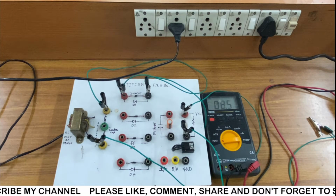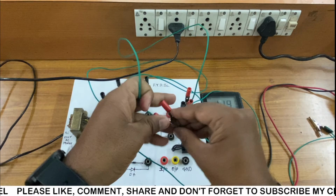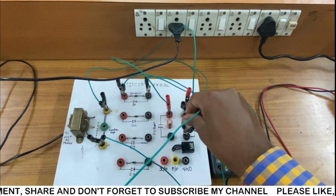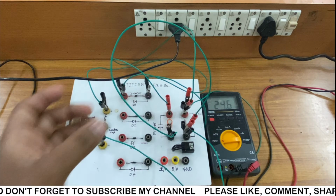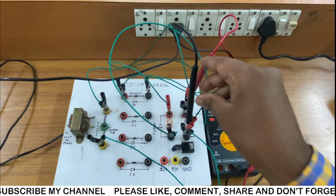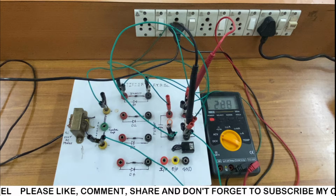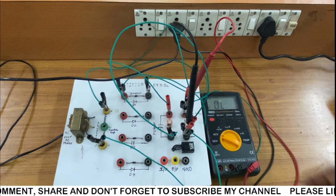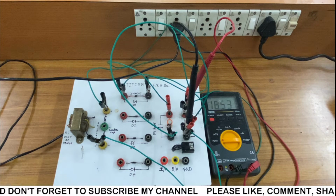I'm going to connect the resistance's one terminal to the capacitor's one terminal, so that the capacitor will be in parallel with the resistor. So we are having a filter circuit inside this rectifier. I'm going to connect the resistance's other terminal to the capacitor's terminal, so it becomes parallel. Now we are measuring the voltage, DC as well as AC. I'm going to measure the AC voltage first. It is varying, so we can say it is zero, it is not stable at all, and the DC is 16.54.